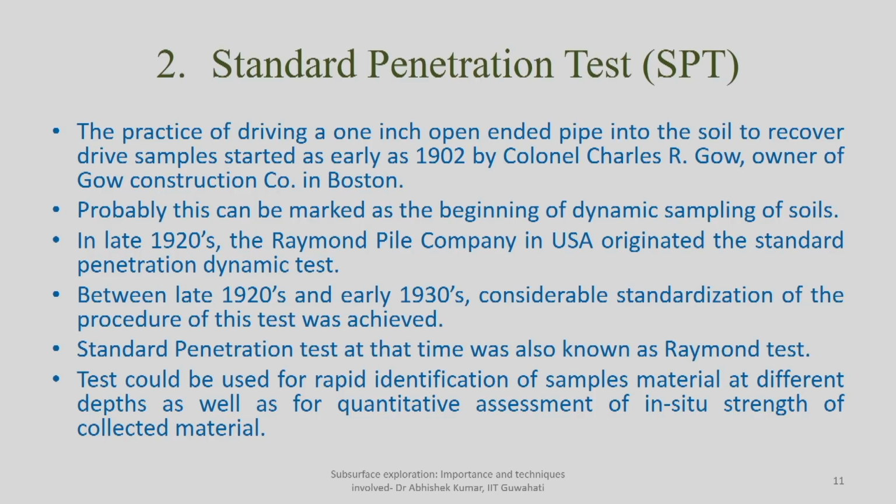Even now, whenever we go for any new sites or try exploring any older sites, and even 10-15 years back, if you start collecting the data, most of what you understand about the soil type and the strength properties of the site comes from the samples collected from the standard penetration test. This test can be used because of the standardization that happened between 1920 and 1930. That time the test was also known as the Raymond test.